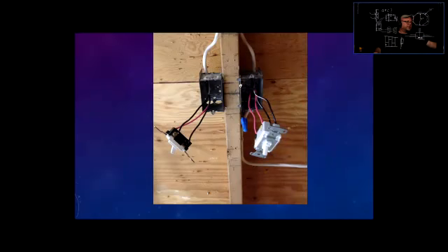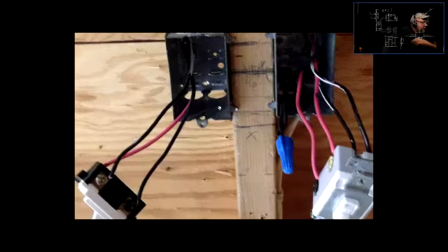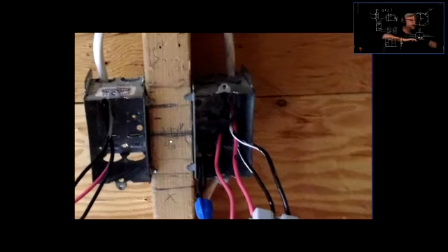Okay, so here's examples of, and now if you take a closer look here, here is the stud. And there are some markings here, those little notches. And between here and here, it's exactly 1/2 inch. So if you align the box with those notches, you will have the box sticking out exactly 1/2 inch right there. These are the helping things here.